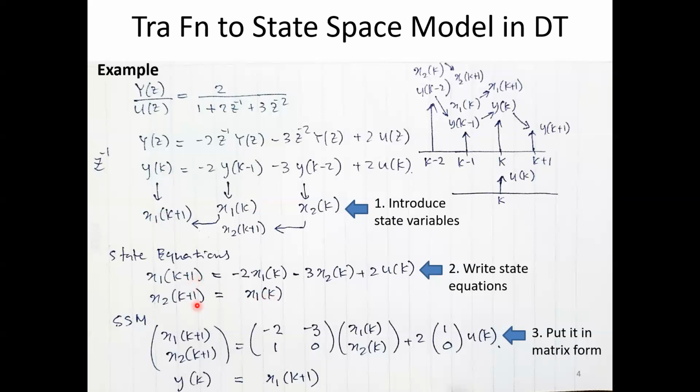And after that, what you do is you put it into the matrix format, right? They are all time k plus 1. And they are all time k, right? And x and k are two different signals. So you assemble x signals using this coefficient matrix, system matrix. This matrix explains how the variables are connected to each other, plus the input signal uk. All right. And you can see there are two equations here. uk appears only in the first equation. So therefore, uk contribution in the second equation is nil. So we have 0 here. Okay.